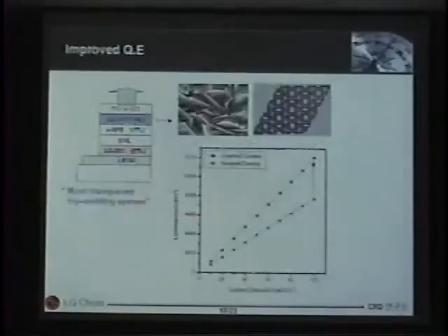And next. But we made the device with an aluminum, lithium fluoride bilayer structure. The deposition of aluminum was first, followed by lithium fluoride deposition. And we use our ETL material. Also, this is commercialized ETL material, and EML, and NPB, and LG101, and ITO, IZO.